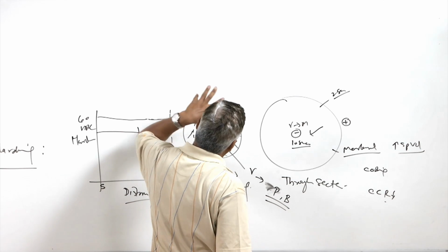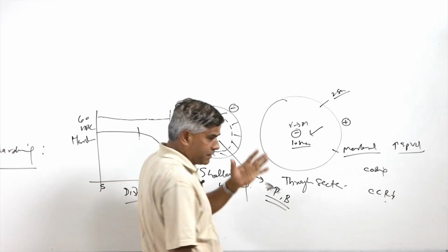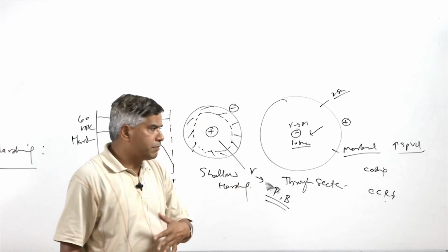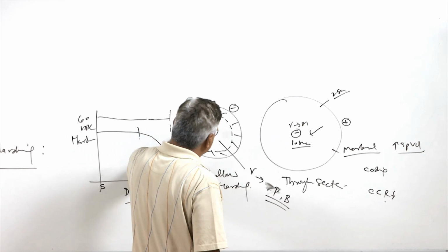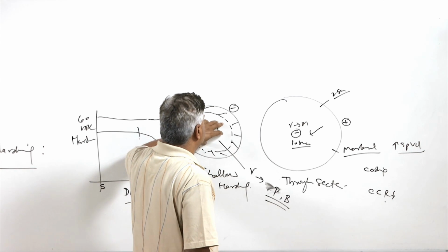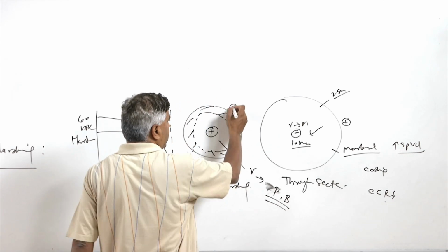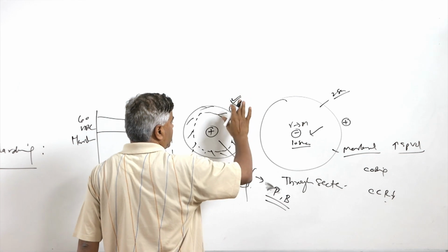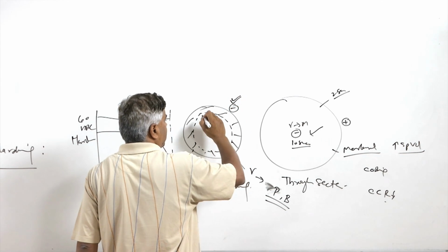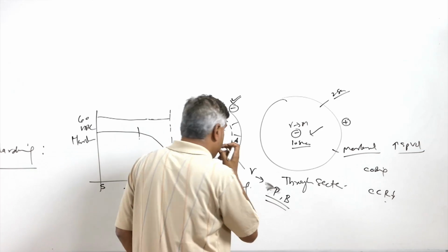Since transformation at the surface occurs with the increase of specific volume, but there is no major change in specific volume at the center, because of this we get compressive residual stresses at the surface and tensile residual stresses at the center.